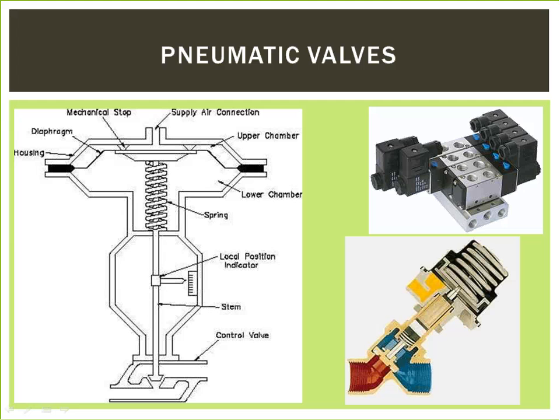In two-way directional spring offset valves, there are two positions they can assume when the connected actuator is inactive, open or closed. In devices where an open resting position is standard, air moves freely through the valve. In a closed resting state, the airflow is blocked. In three-way valves, one port is always open. In such cases, a closed resting state usually results in blocking the airflow port, so pressure isn't moving unless the device is turned on.